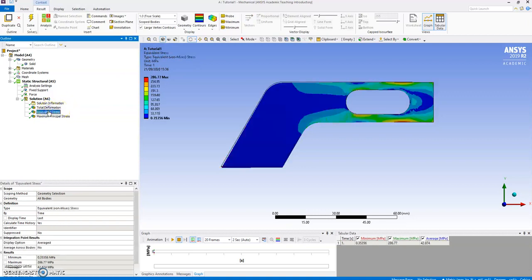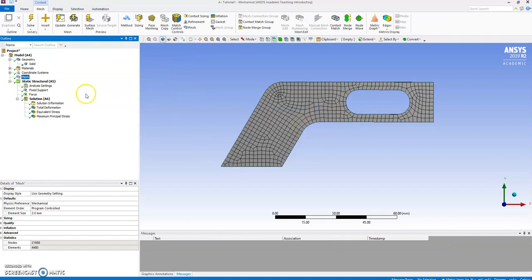Let's check the stress, now the maximum stress. Ooh, maximum stress at around 300 megapascal. Now, something you have to keep in mind very quickly is that you have to ignore the 0.77 here at the top. There is no way that the stress is accurate at that point. This is an approximate method. I've got a mesh, and the actual final results will depend on the quality of the mesh. In fact, we'll do that in the second tutorial.